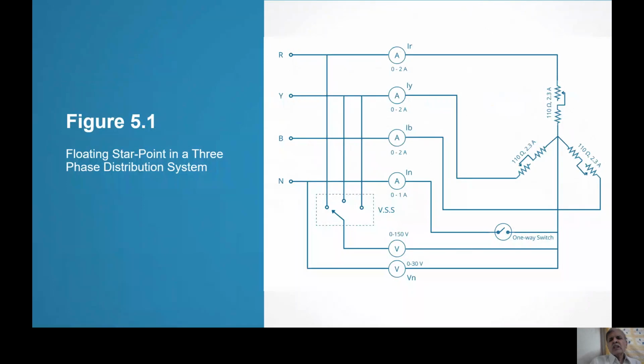We are using this very simple figure. Very simple in terms of connection also, and very simple in terms of money also, because we need 4 voltmeters and 2 ammeters. We need one-way simple switch which we use in our houses, because there is no heavy current passage. A 5 ampere switch is enough. Current is not the criterion. Our main point is that the voltages are not remaining constant. That is what we want to observe.